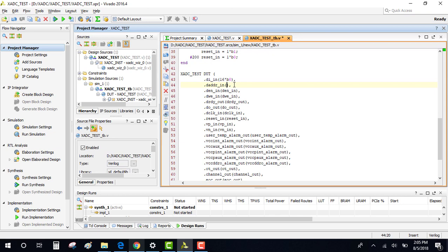Okay, but I'm going to put here an address, that is basically 2'b10, and you can understand why I did that. And not 0, it's another curly bracket, and this curly bracket is also here. Okay, this is basically a concatenation.